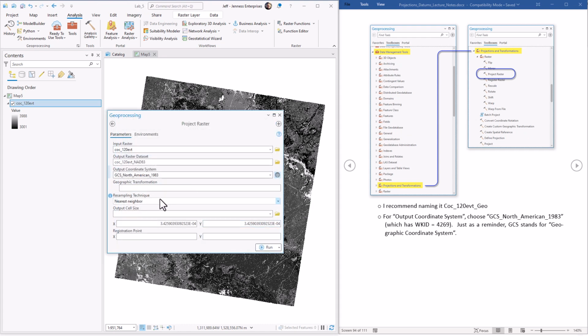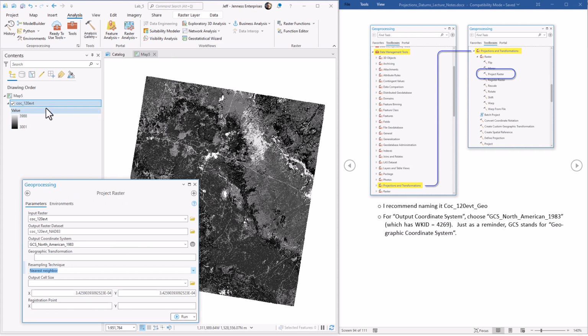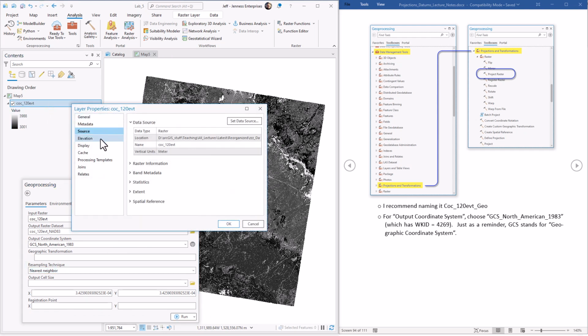We're going to resample using nearest neighbor, and that's because this is actually a veg type raster. And for these type of categorical data sets, you definitely want to use either nearest neighbor or the majority. The other two, bilinear and cubic, will take an averaging function. Nearest neighbor and majority will make sure that all the new raster values existed in the original data set. And maybe let's change these numbers so it's actually something we're used to seeing.